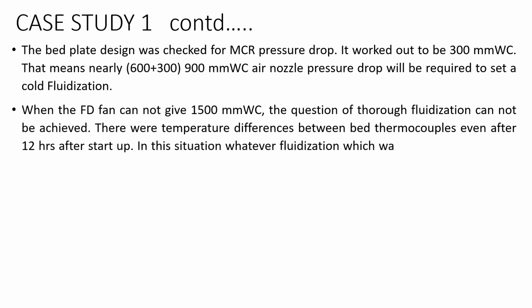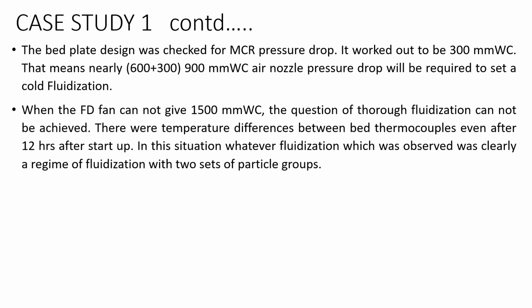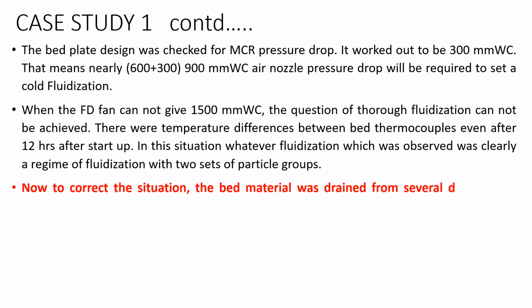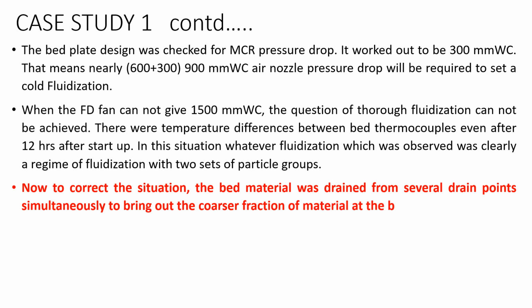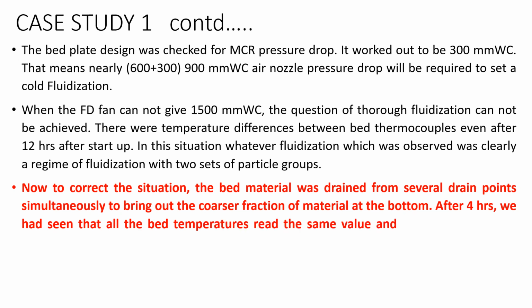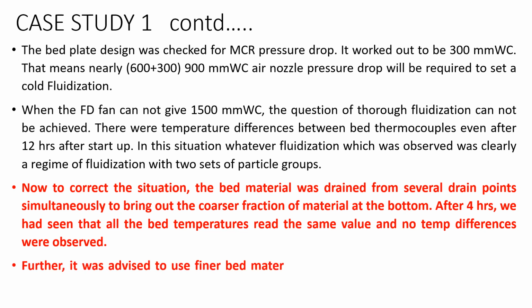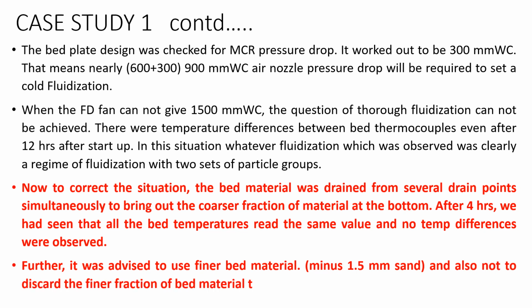So there are temperature differences between the bed thermocouples even after 12 hours after startup. Now in this situation, whatever fluidization was observed was clearly a regime of fluidization with two sets of particle groups. Now to correct the situation, the bed material was drained from several drain points simultaneously to bring out the coarser fraction of material at the bottom. After 4 hours, we had seen that all the bed temperatures reached the same value and no temperature differences were observed. So further it was advised to use finer bed material, that is maybe minus 1.5 mm sand, and also not to discard the finer fraction of the bed material, that is less than 0.5 mm.